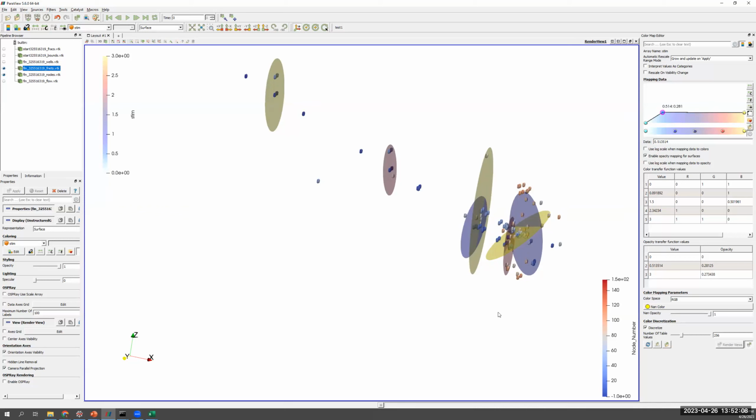How do you do variable rate injection in GeoDT is another question. Variable rate injection applies more to the details of the stimulation design. GeoDT does have the ability to do stimulation, but it does it in a simplified way. So variable rate injection is not one of the parameters currently embedded in this example script.